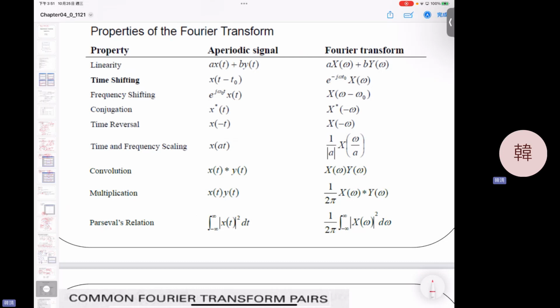If I multiply the Dirac comb function here with my image, I'm going to sample your signal. What do you do? You multiply by the sampling function. You multiply the comb function times your signal, right? So what happens in the frequency domain? It becomes your X(omega) convolved with the comb function.